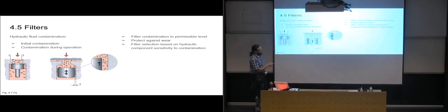And the same if you have a piston. If you get too large particles ending up on the side of the piston, because the piston will always need to have some room so that it won't scrape along the edge all the time. So it will need to have some room here. And if the particles get too big, they can actually be trapped inside here along the side of the piston. And if they are then rotated so that they really get jammed in there, then you're going to create a lot of damage to the sides of the cylinder and also to the sides of the piston.